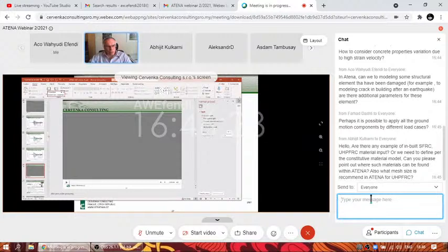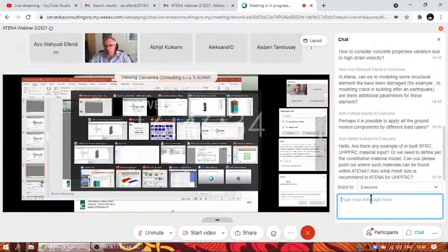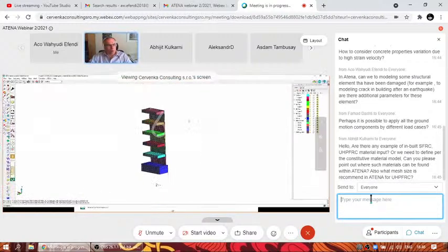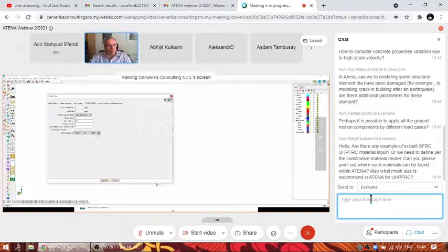Either we are using the Rayleigh damping, maybe I show the GiD interface to make this clear. Under this problem data, you define damping either by coefficients, where you define directly the coefficients for the mass matrix or for the stiffness matrix. But these, in my opinion, are a little bit difficult to identify. So much better is to define these psi parameters for the various eigenmodes, which I think are easier to estimate.